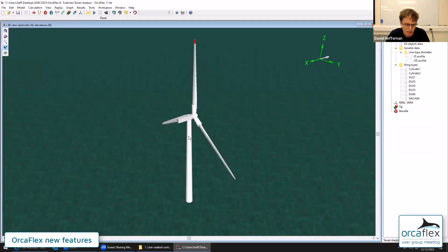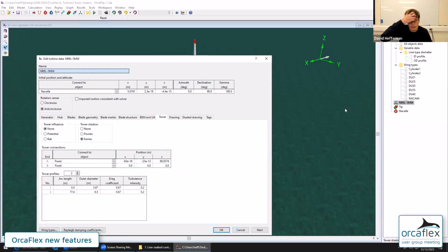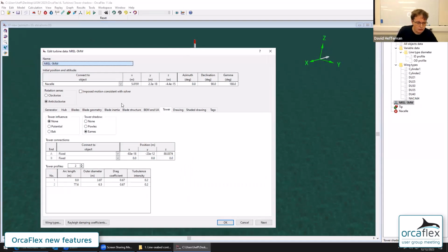So there's a velocity wake deficit. If the wind hits the tower, it has to go around the tower, and that influences significantly the aerodynamic field seen by the blades. There are a couple of standard methods widely used in the industry to model this effect. This effect's called tower shadow.